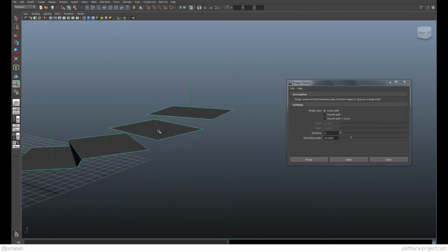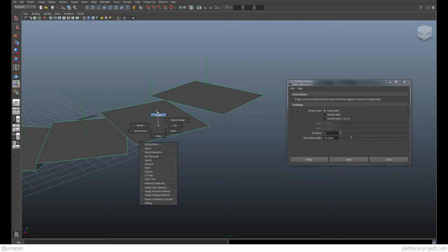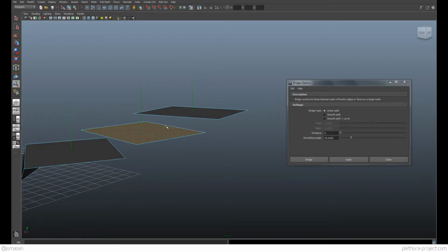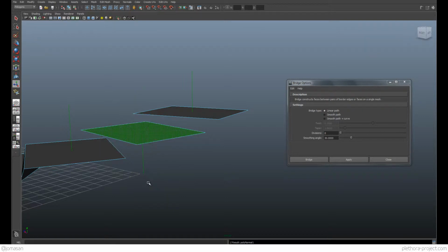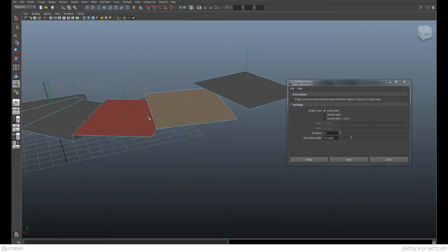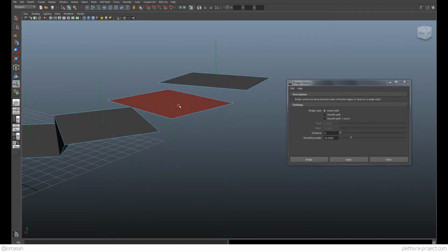But maybe for some reason your geometry, like let's go into face mode on this guy, maybe your normals, I'm going to go into the normals, and I'm going to reverse the normals. They could be flipped, right? I'm just saying that in case you're modeling something around and maybe you're not aware, maybe your normals are facing the opposite direction.